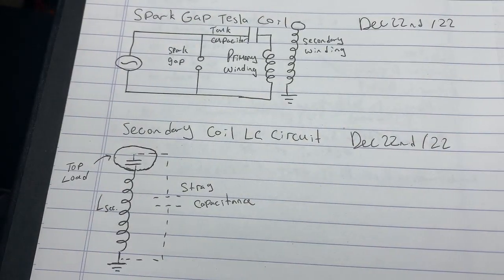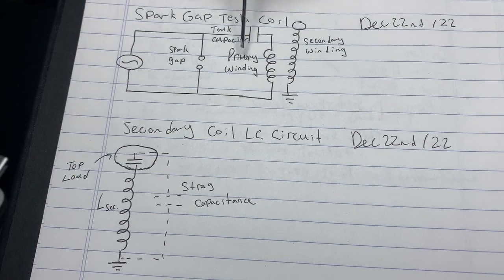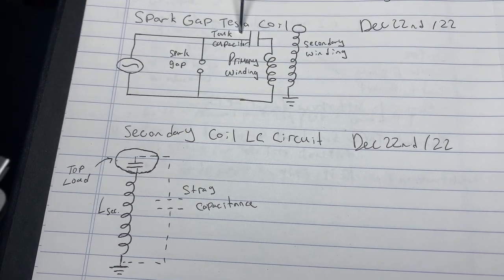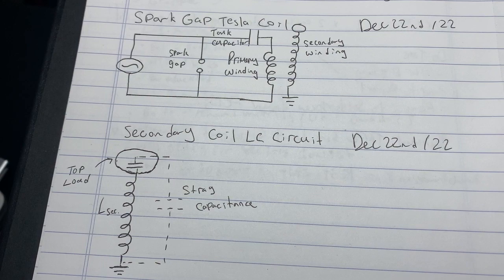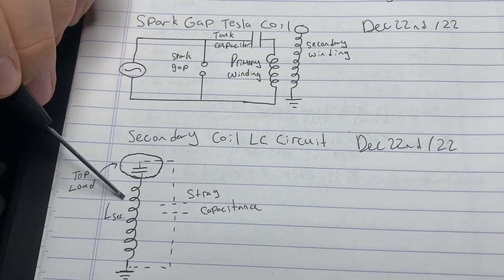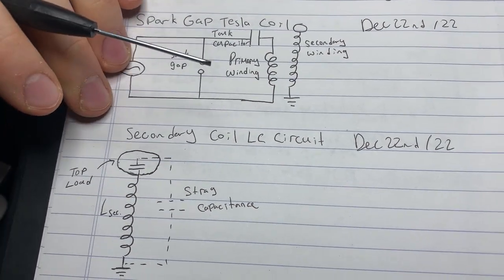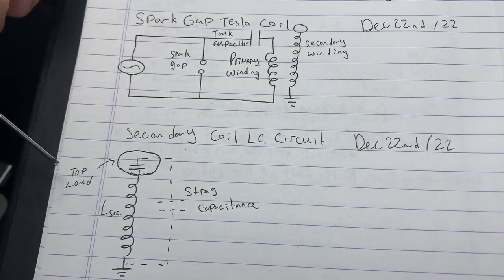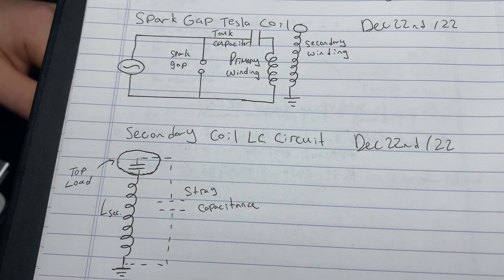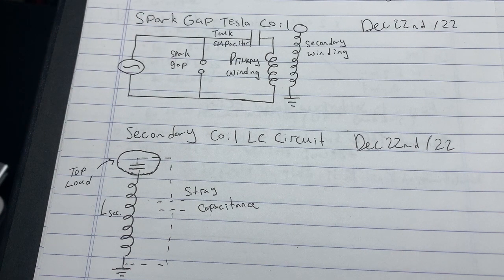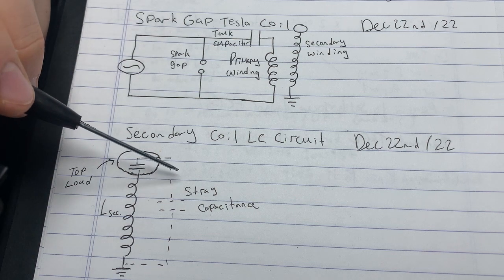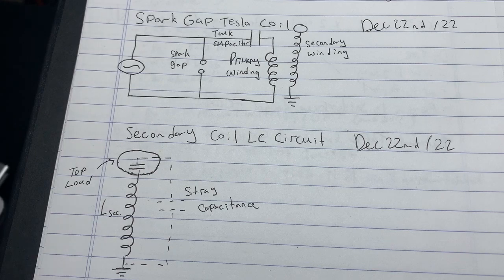In a Tesla coil, there are two LC resonating circuits, the primary and the secondary. The primary circuit can be in the parallel or series configuration, while the secondary is always in the series configuration, capacitively coupled to ground through the air. The sparks, called corona discharge, are created when the charge in the secondary coil tries to make its way back to ground as part of a capacitively coupled circuit.